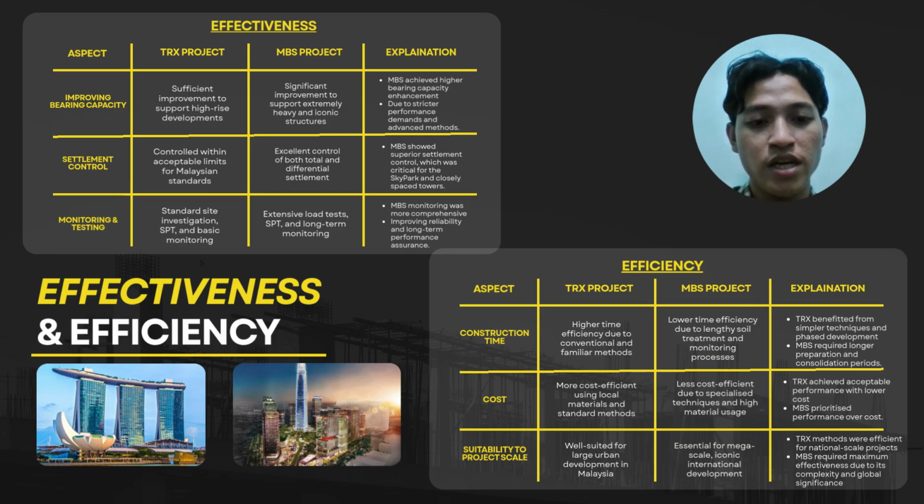In contrast, the Marina Bay Sands project required much higher performance due to reclaimed marine clay and extremely heavy iconic structures. Preloading with PVD was extensively applied to accelerate consolidation and control long-term settlement. Vibro replacement installed compacted granular columns to improve soil strength, drainage capacity, and pore water dissipation.